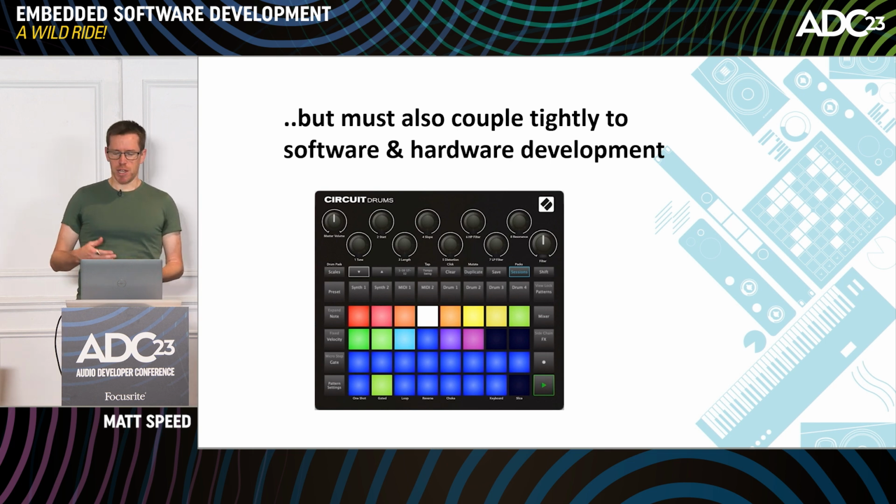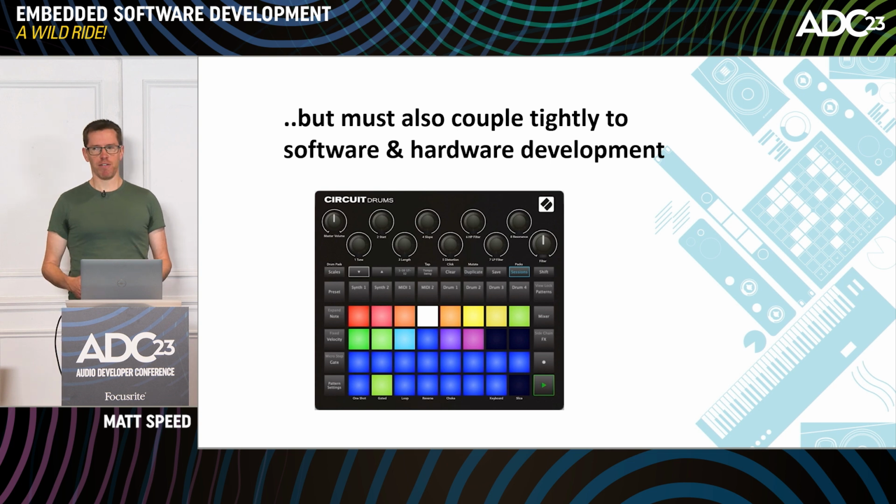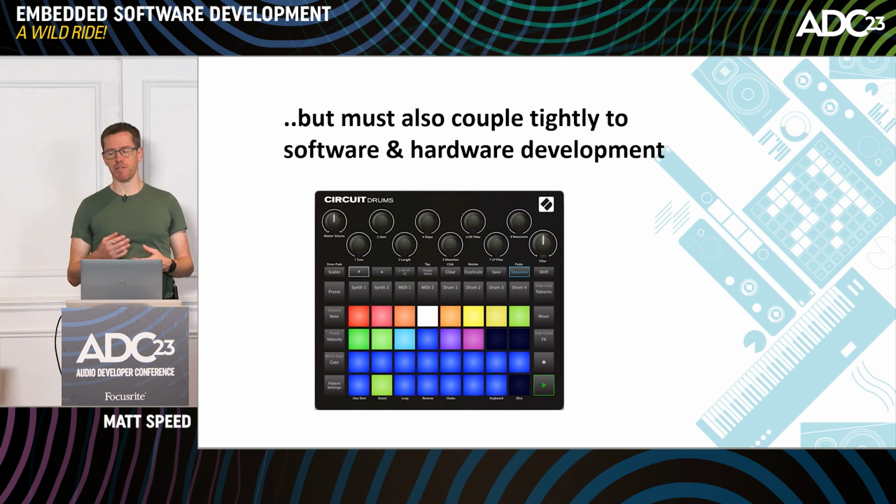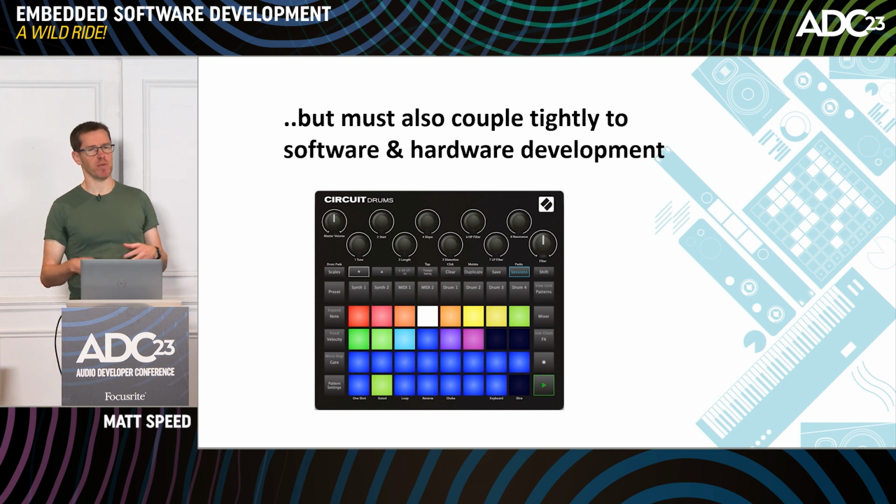So we keep getting new updates of boards, and when these arrive, big box plonked on the desk of the firmware engineer. And the firmware engineer has to step aside and bring the board up. This means checking everything is as it should be, checking the power supply is sane before you even power it up, checking it can do everything it did before, and then checking any fixes are good. So if you fix something for signal integrity, has that problem gone away? Have you just played whack-a-mole and created a new problem somewhere else? This means the firmware engineer periodically stepping away from a typical sprint cycle to go and do some bring-up work.